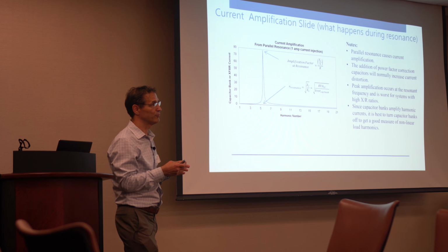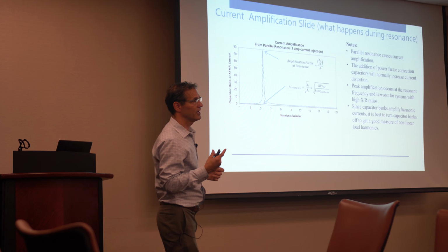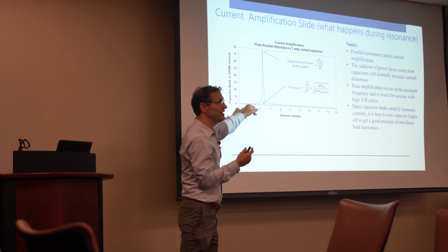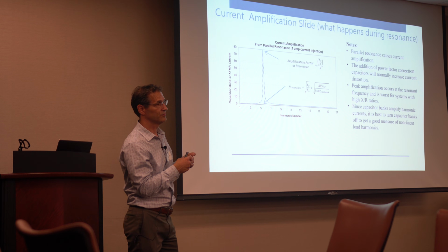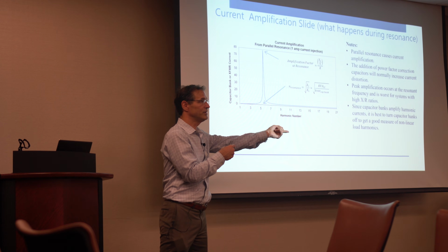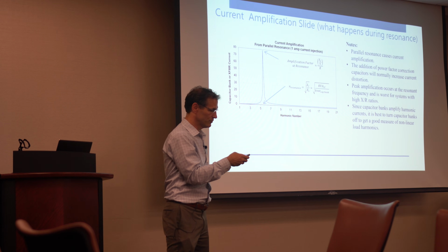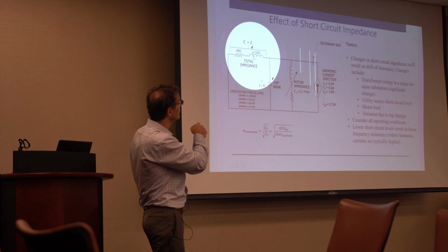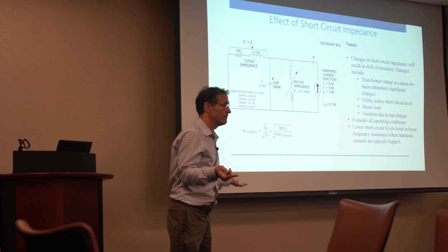So I've got a drive that only puts out 1 amp because it's a high pulse number drive. But if it's putting out 1 amp, it becomes 80 in the capacitor bank. It becomes very significant in the capacitor bank and also in the source impedance, which makes you fail 519.